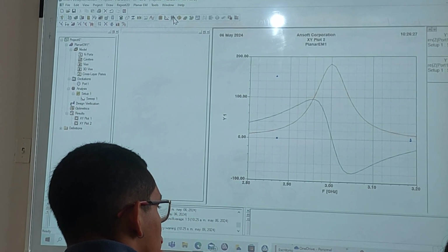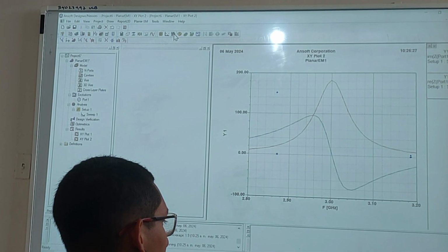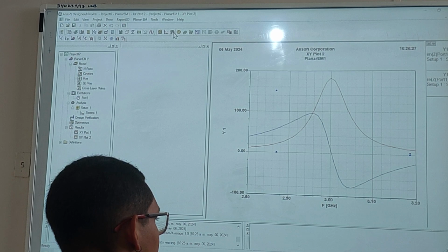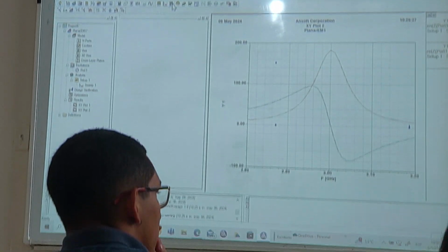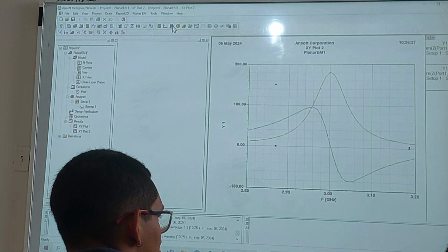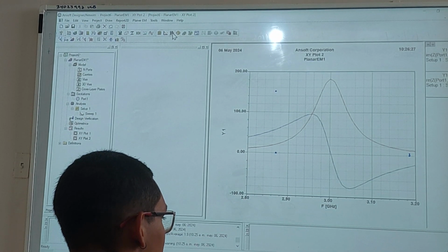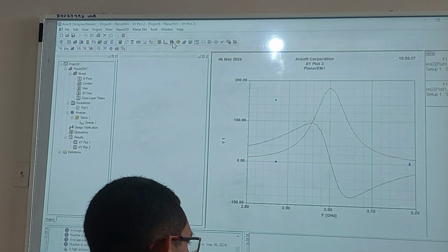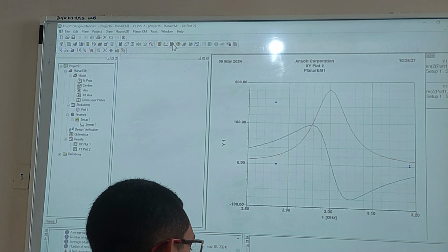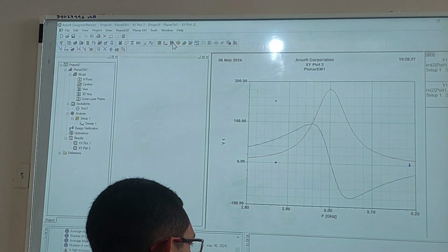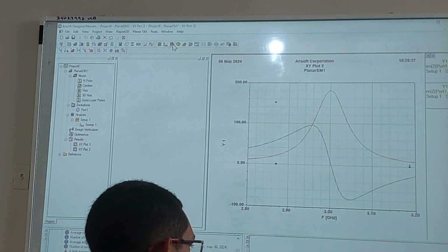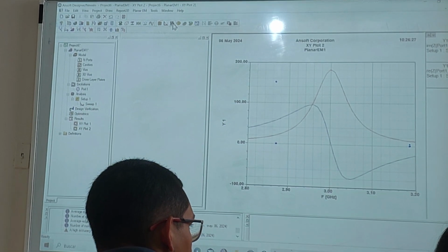Then we put the transmission line, and if we select the solution with low frequency, this will be the coupling system. And this width will be more or less 4.5 millimeters. Then here, these two structures are very similar. And because both are very similar, the antenna probably works with this patch and not with it.